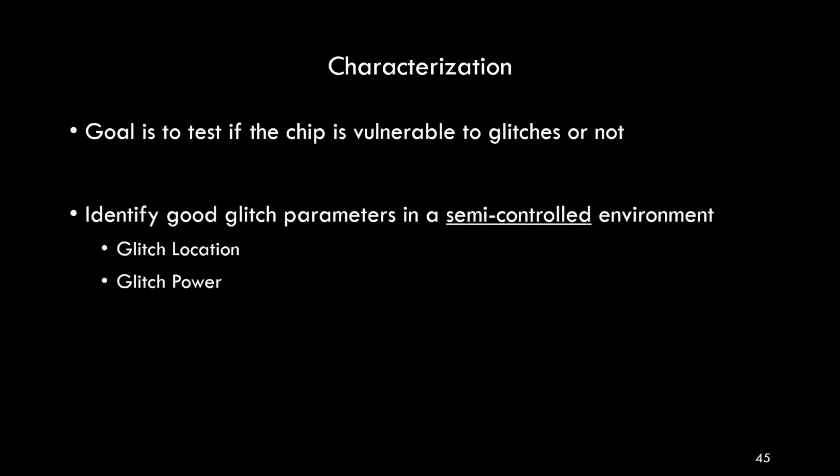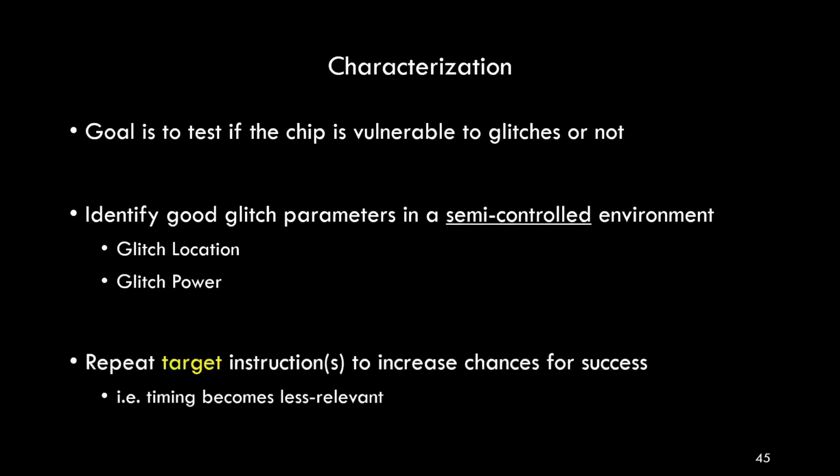So this allows us to identify good glitch parameters in a semi-controlled environment, because we control the software and we can write this software in a certain way that we can more easily deduce certain conclusions from the behavioral changes that we detect. So for example, it also allows us to determine which locations on top of the chip, with what type of glitch power, are vulnerable to the EM glitches that we are injecting.